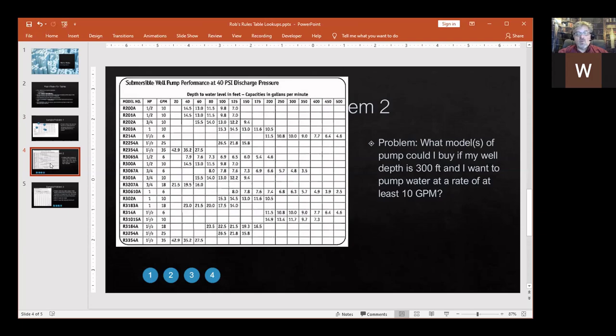So when you're picking the right well pump, you want to make sure that for the depth of your well, that is how far up your pump needs to pump, you get the water pressure you want in your house. If you oversize it, then your pump will be cycling. It'll be pumping really fast, really hard, and then stopping. And then pumping really fast, really hard, and stopping, right? And you'll be wasting energy, and probably require more energy than you need, and it won't be an ideal scenario. So ideally, you want to size your pump to just the right amount to pump up to the right pressure given the height of your well.